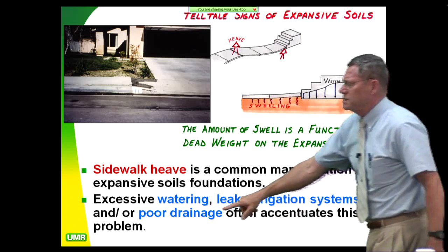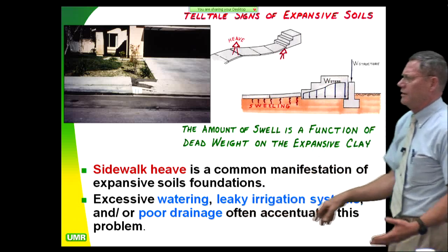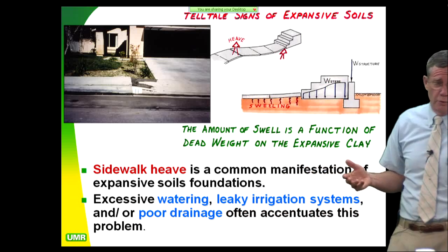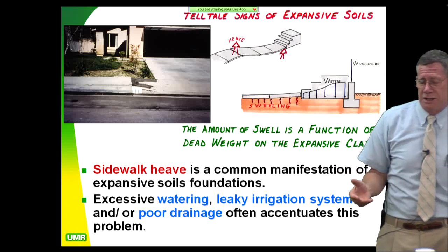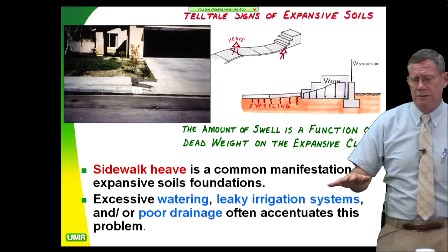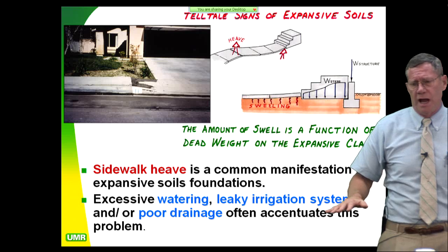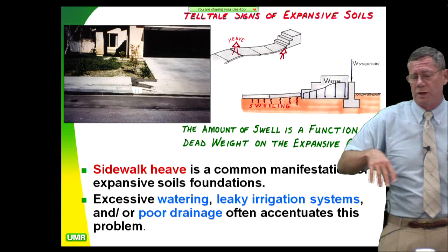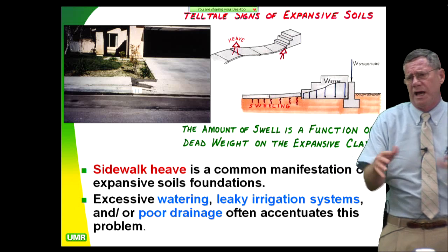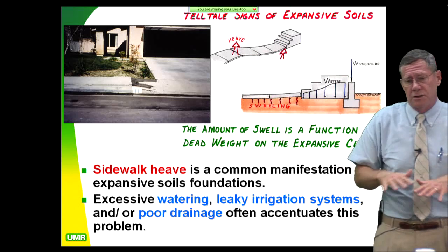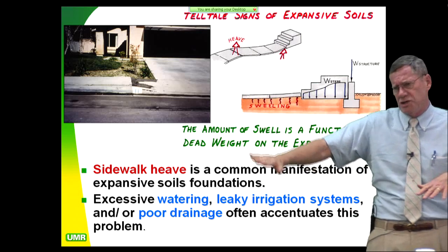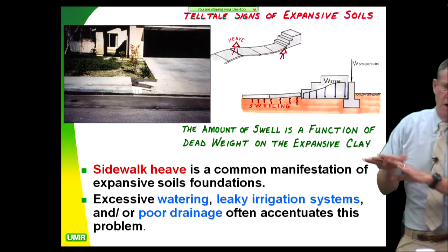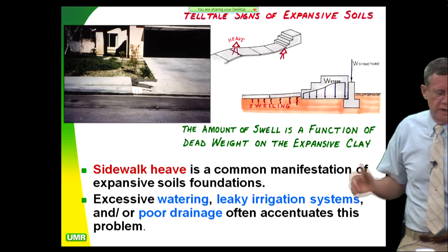And the other thing is poor drainage. If you have some area that has poor drainage, you're going to have problems. Now, a lot of people don't start with poor drainage. They get poor drainage because of landscaping, because of the ground lifting up a quarter inch to half an inch a year with root activity, root biomass, and worms. And so what used to be a 3-inch depression next to the house, 20 years later it's gone. And you got water ponding along there, even though it wasn't graded that way.